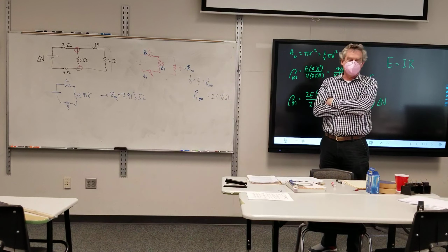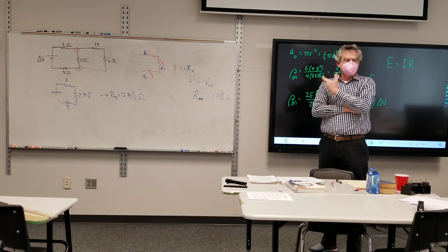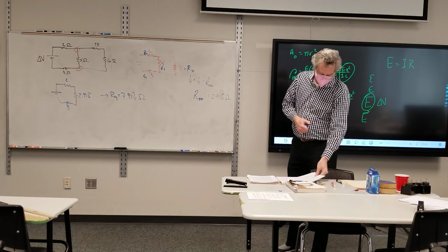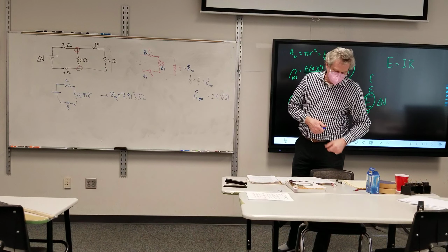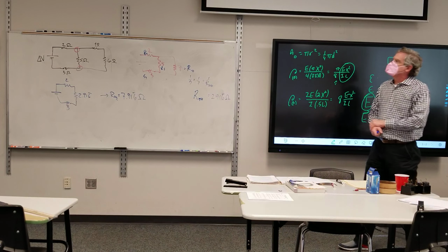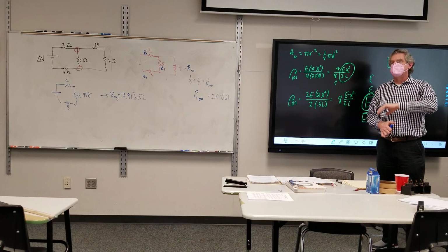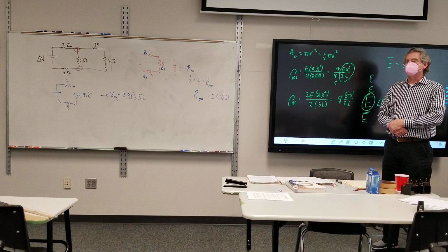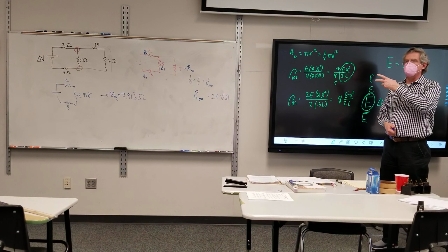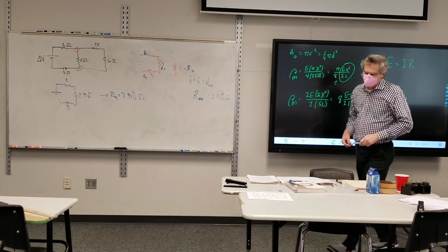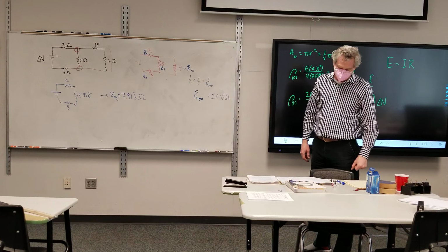And you can pretty much be sure there's gonna be some problem where you have to find an equivalent resistance and equivalent capacitance. All right. Questions on this? Capacitance formulas are just the opposite of resistance. You'd still do it in the same order, just a different formula every time you combine them. And that's part D, where I say, hey, pretend that they're all capacitors with units of farads instead of ohms.